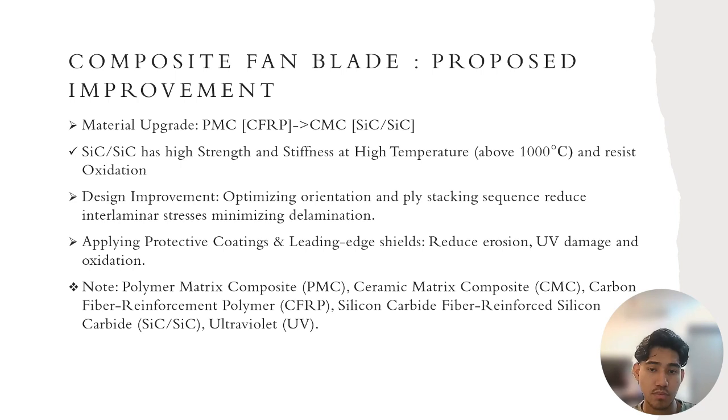So for the proposed improvement of the composite fan blade, upgrade the material from PMC CFRP to CMC, silicon carbide. Silicon carbide has high strength and stiffness at high temperatures above 1000 degrees Celsius and resists oxidation. Design improvement: optimizing orientation and ply stacking sequence to reduce interlaminar stresses and minimize delamination, and applying protective coatings and leading edge shields to reduce erosion, UV damage, and oxidation.